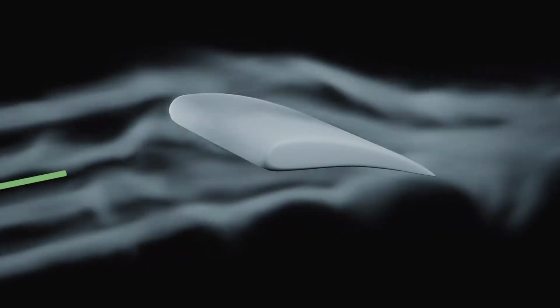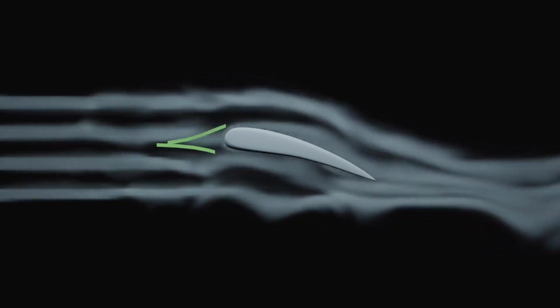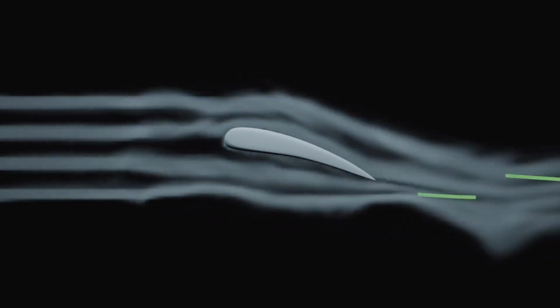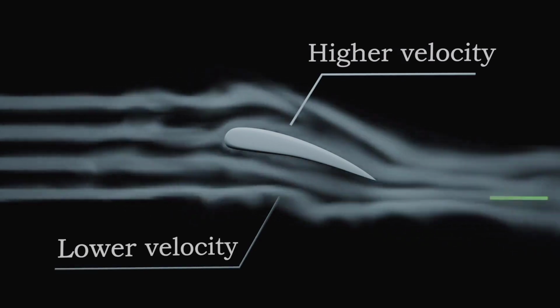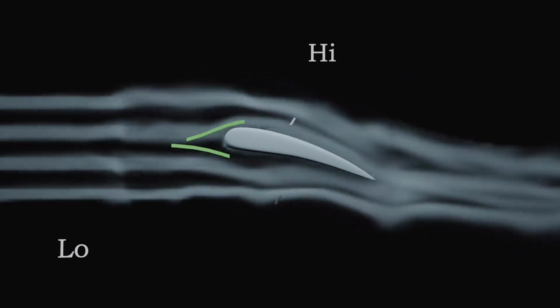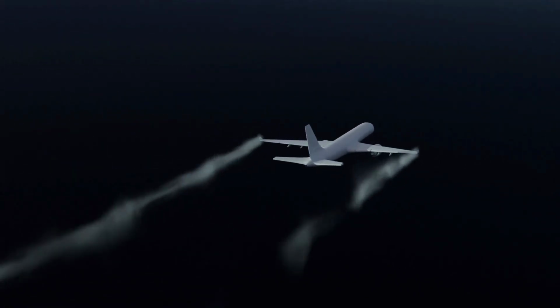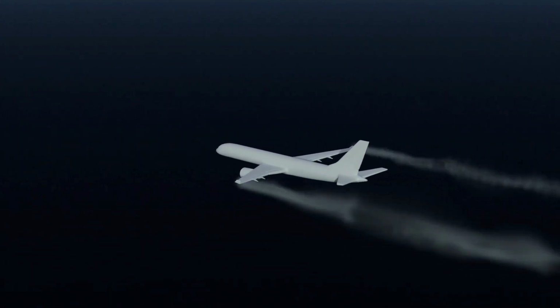In fact, experiments have shown that the air on the upper side reaches the trailing edge much earlier than the air on the underside. So the theory based on Bernoulli's principle attempts to explain lift by highlighting the lower pressure above the wing due to the faster airspeed. However, as we've seen, the reason for this is not the equal transit time theory. Many researchers advocate for the next theory we're about to explore, as it offers a more intuitive and physical explanation for why an airfoil generates lift.